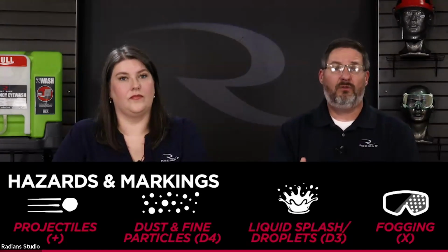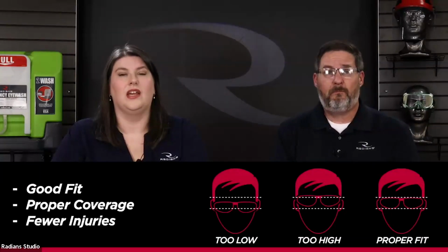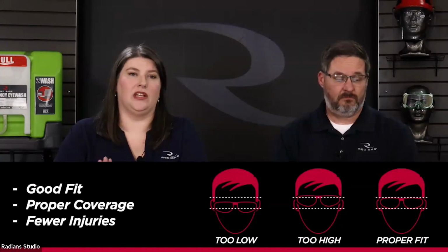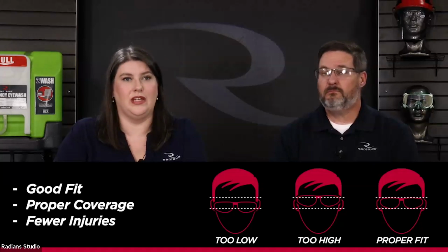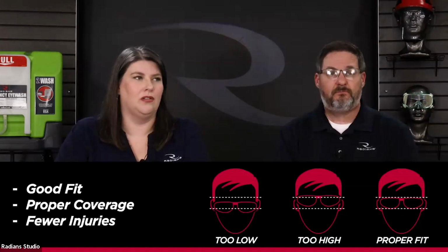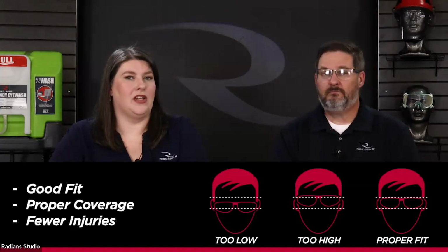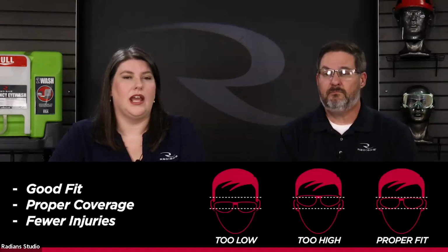Now, there are other things that you have to consider. Yeah, so, once you've determined what your hazard is, you've selected the proper device, whether it be a safety glass or a goggle, and in most chemical environments, it's going to be a goggle and maybe a face shield, you always want to make sure that you have the proper coverage and the proper fit.